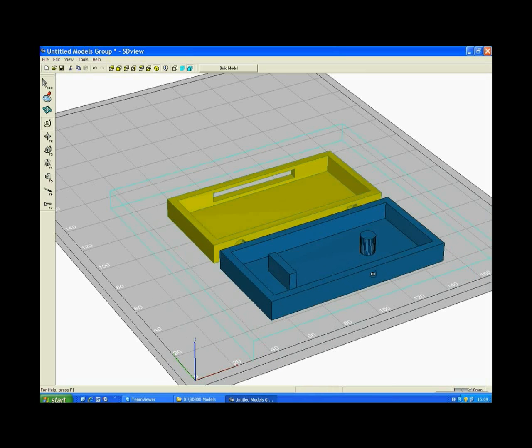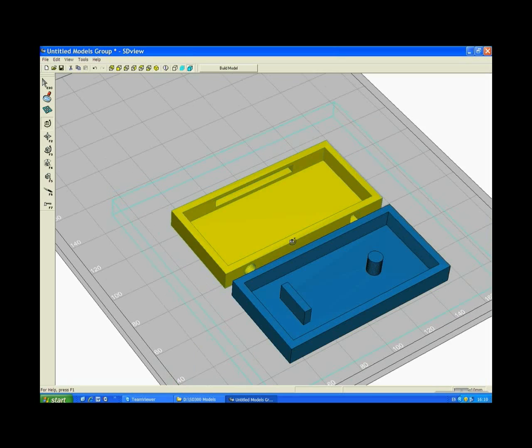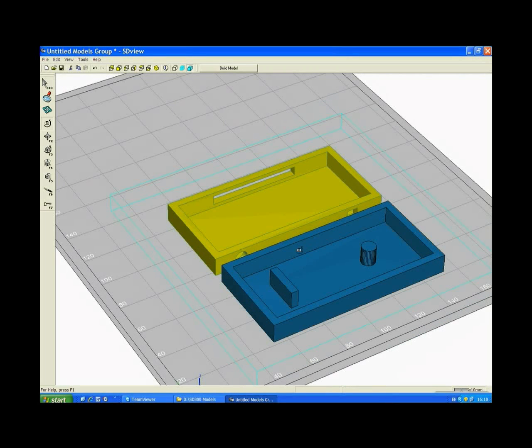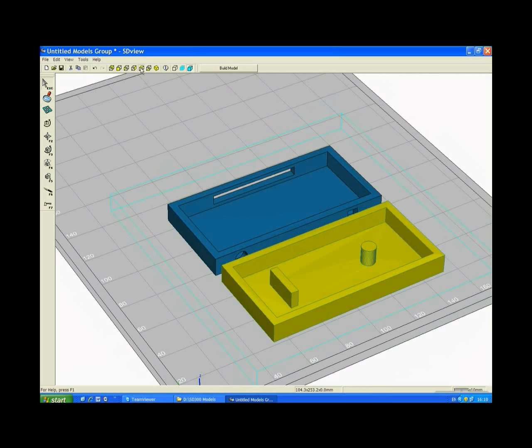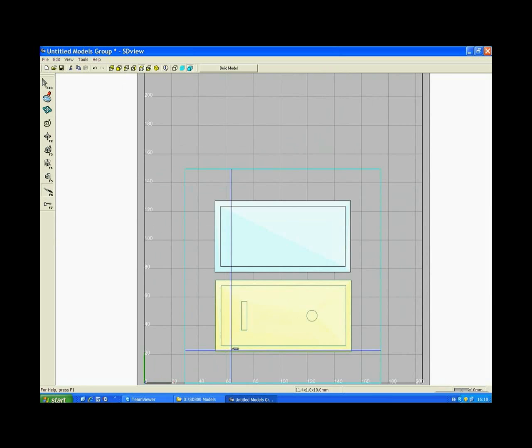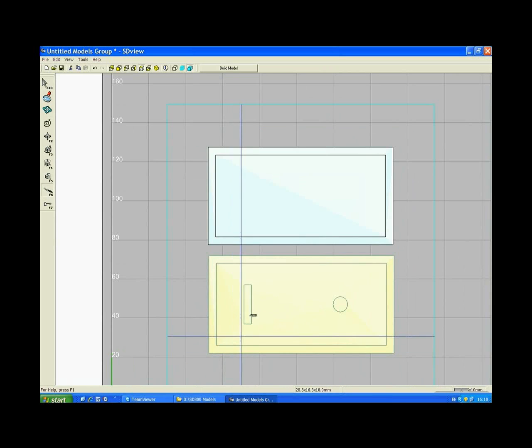The first model is a closed rectangular box with a wall and a post. The second model is a rectangular box which has openings on the X and Y axes. These two examples will show us how to place peeling cuts in order to peel around features in the most effective way. First, let's look at the first model selected. Using the top view, we will place peeling cuts through the center of the wall and one from the wall to the center going through the post.